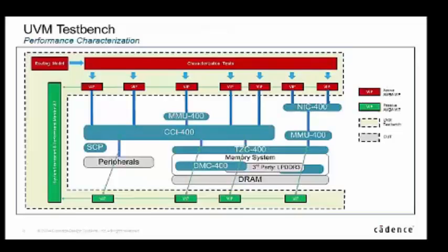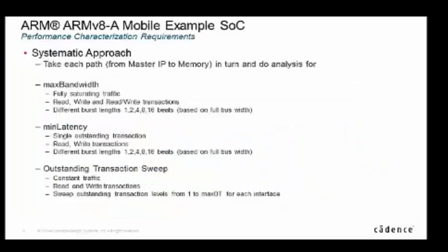What we also discovered is that, in some senses, the interconnect can be the throttle, not the DDR controller, depending on which particular clock frequencies you set up, and which DDR standard you use. You can change whether it's the interconnect that's throttling the performance or the DDR throttling the performance. You would hope that it would be the DDR because you want to run that as fast as you possibly can. However, not every system is the same.